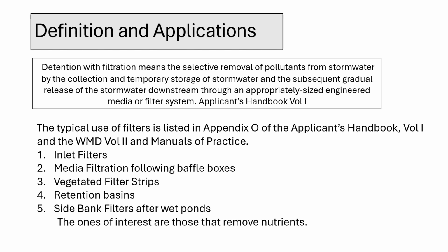In practice, the focus here is specifically on the removal of nutrients, particularly total nitrogen and total phosphorus. Filters are typically deployed after settling has already occurred, meaning particulates have been removed first. This sequencing is important because it significantly extends the life expectancy of the filter media.